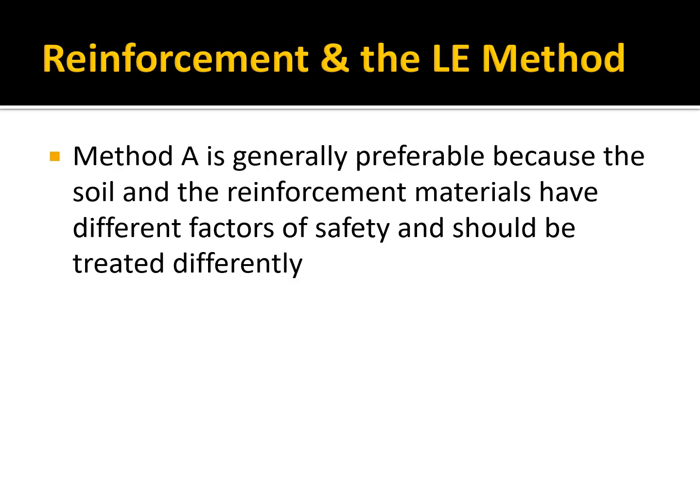So method A is generally preferred because the soil and the reinforcement materials have different factors of safety and should be treated differently.